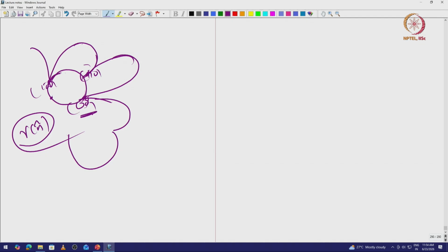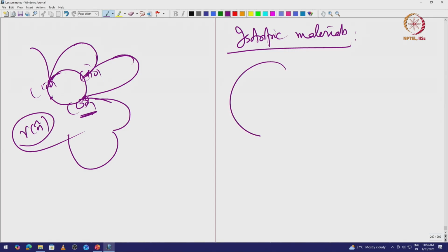The value of gamma determines which facets you are seeing and which facets you are not seeing. Now, we also said in the case of isotropic materials, if you remember, I have gamma as a function of n. In an isotropic material I can again do a tangential construction, a circle tangent, and then all these surfaces are equally stable or equally unstable.